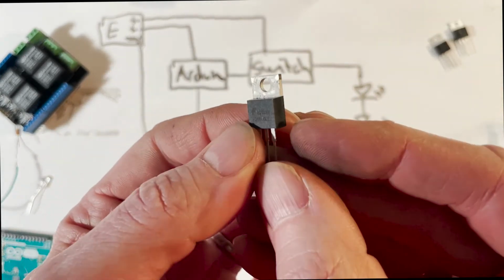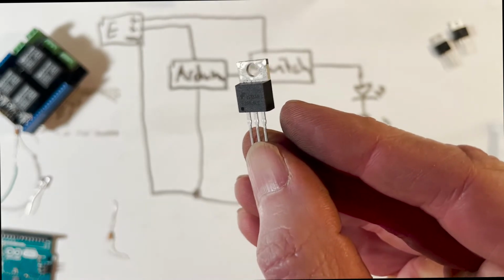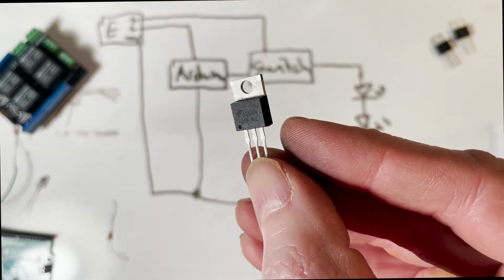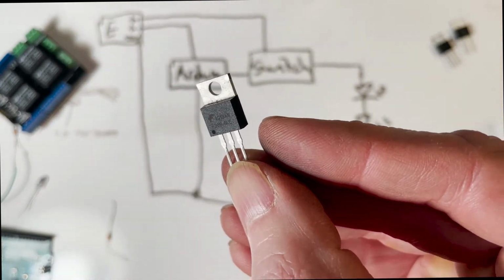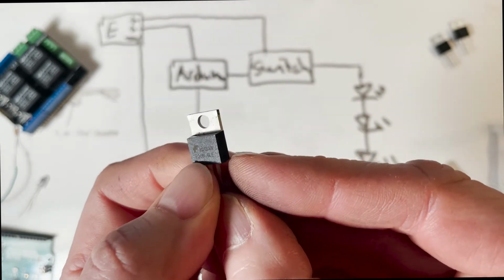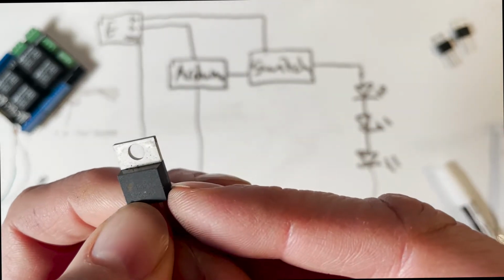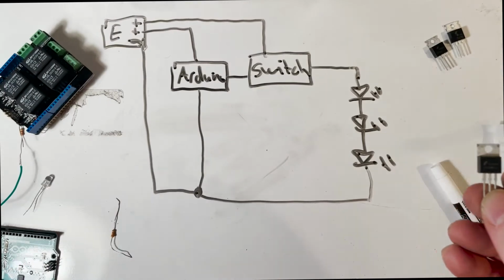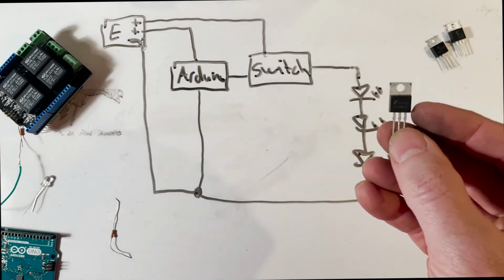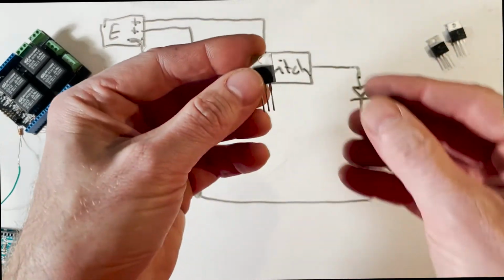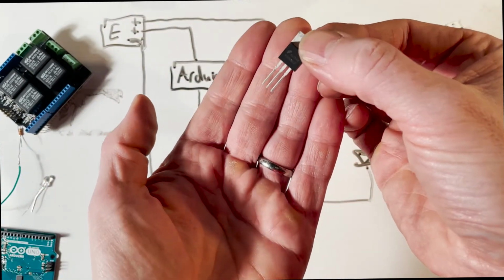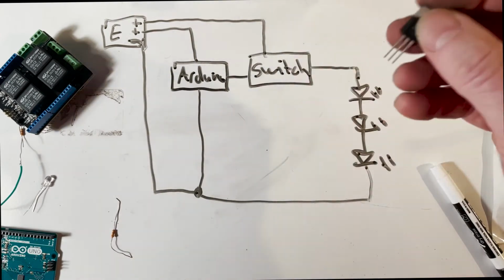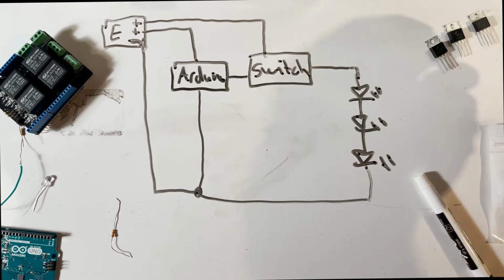But the important thing to do is to make sure you read the numbers, because even if something is in the box, I'll bring the light in a little bit. Yeah, we still can't see it with the camera light, but I could see it, and it says P30NQ something. I can look up that data sheet and make sure that this is actually a MOSFET. And when I look up the data sheet, I'll also get instructions on the pins, because these pins have to be connected to the circuit in a certain way, which we're not going to get into in this video. I just want to tell you that.